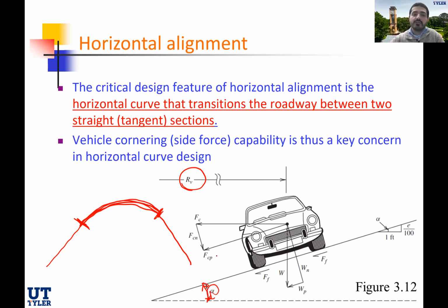Without that super elevation, by the laws of physics, if you're driving at even a certain speed, you can go out of that curvature, and that's why we have the concept of super elevation, to keep you inside. We see this more in car racing competitions, where the super elevation, or that angle, is very high because it's proportionate to the speed of the vehicle. If you are racing, you are at much higher speeds, and without that super elevation angle, the car will be drifting off of the curvature.